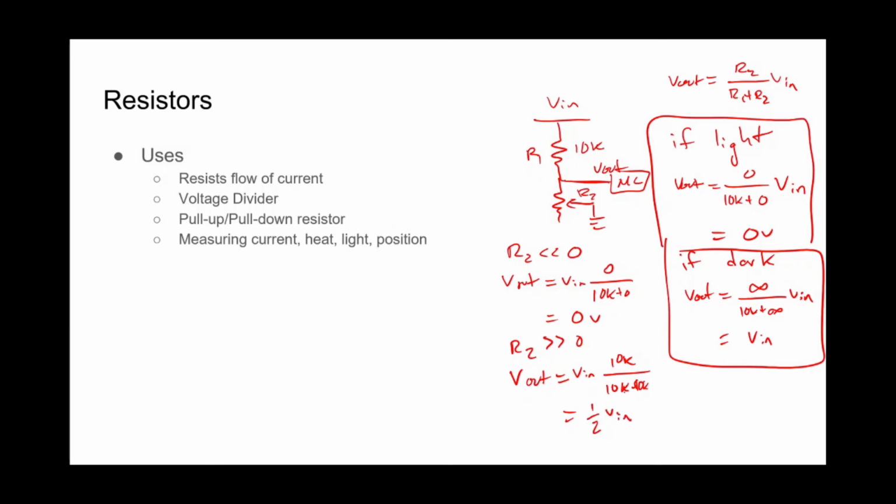So you can see it's not giving us all of Vn, but that still gives us a decent range. In this case, we would probably lower the value of whatever Vn is. We don't want to go too small because remember all of that voltage drop is still going to have to go through here. But we could fluctuate the value of R1, or we could choose a specific R1 to meet our needs. So anyway, getting back to business, this is how we would use a voltage divider with a variable resistor, whether it's a potentiometer or a photoresistor or a thermistor, to measure certain things.